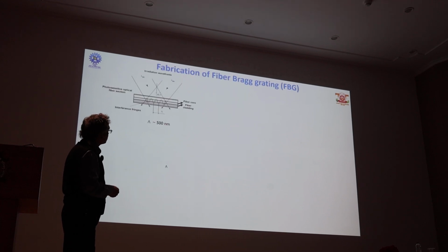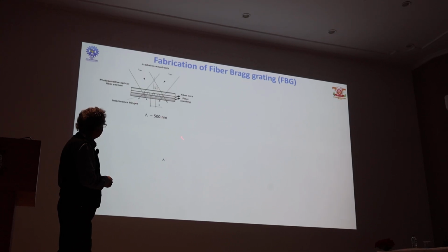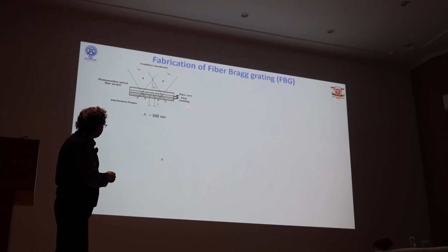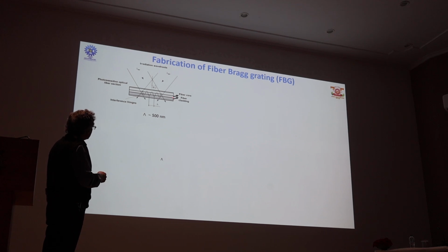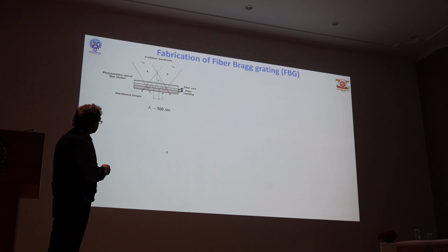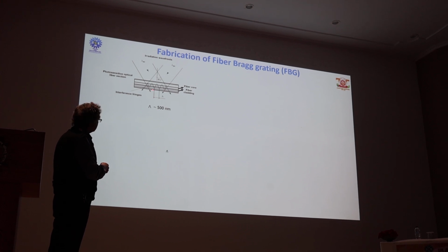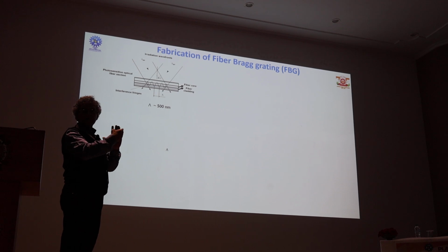So what we do in an optical fiber to conceive this bandpass filter, now we are seeing this is a small piece of optical fiber along the propagation direction. This is the core region. Using ultraviolet light, we cast a fringe on this core material. An optical fringe means it is a dark and bright pattern.